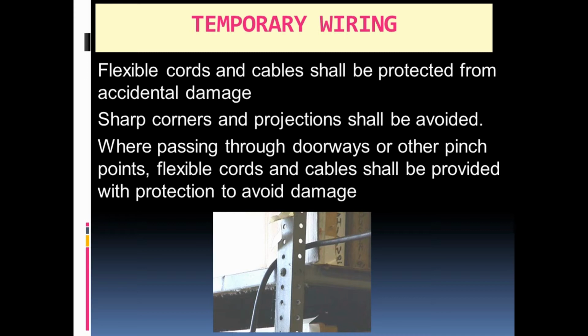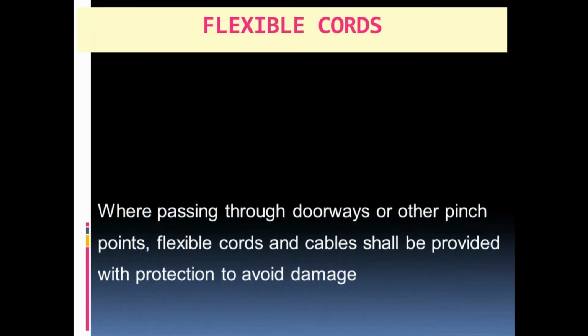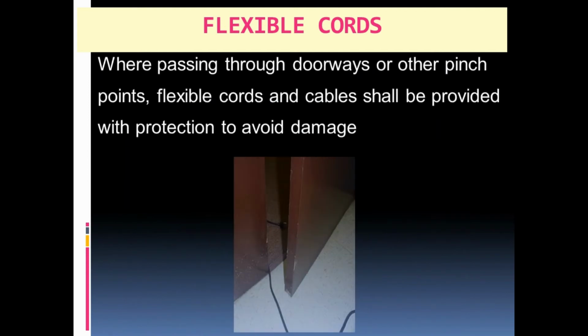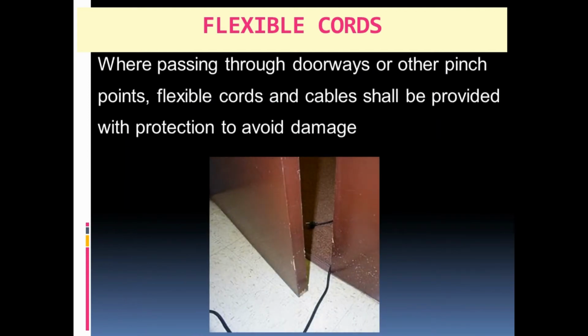Flexible cords and cables shall be provided with protection to avoid damage. Flexible cords. Where passing through doorways or other pinch points, flexible cords and cables shall be provided with protection to avoid damage.